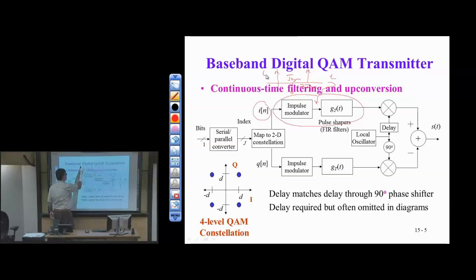So the areas here would be I0, I1, I2, and so forth. And then we're going to pulse shape this to limit the bandwidth, right? The impulse train has infinite bandwidth. All right. So we've talked about this already. And then we're going to upconvert this with a cosine. So this is basically our cosine modulation.